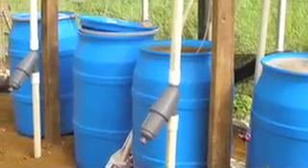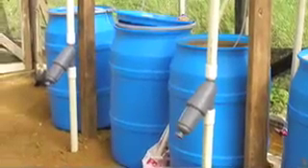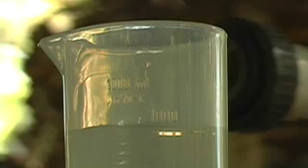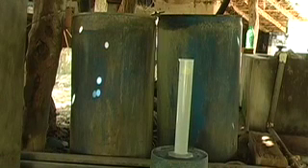In more advanced fertilizer systems, each fertilizer is diluted in its own tank. The main concern is not to mix calcium nitrate with the other fertilizers, since a combination causes clogging of the emitters. Typically, 1 liter of each concentrated nutrient mix is added to 100 liters of water.